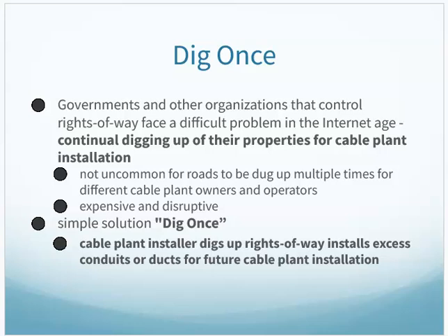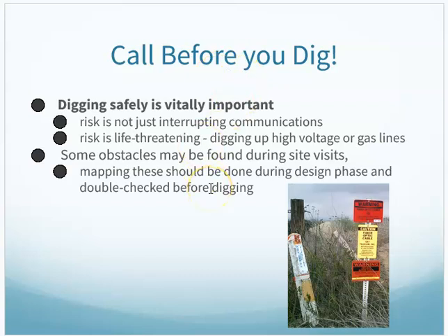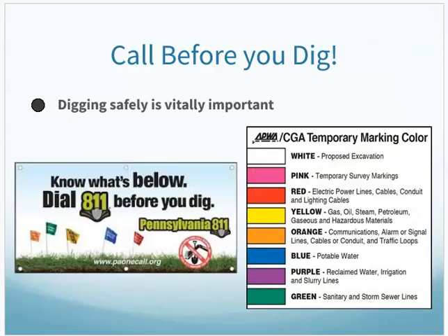This reminds us of when we get to the point of looking at digging for trenching, whatever. There are sites and utilities out there where you check before you dig to make sure that you're not crossing any kind of utility paths or digging up a utility. Last thing you want to do is dig up a sewer line and have to repair that whole mess, if you will. So there are sites where you can say, this is the plan, this is the path we're going for. Please let us know if there are any utilities here, and they literally will come out and start marking with flags, indicating what is in that area to know what you're avoiding.